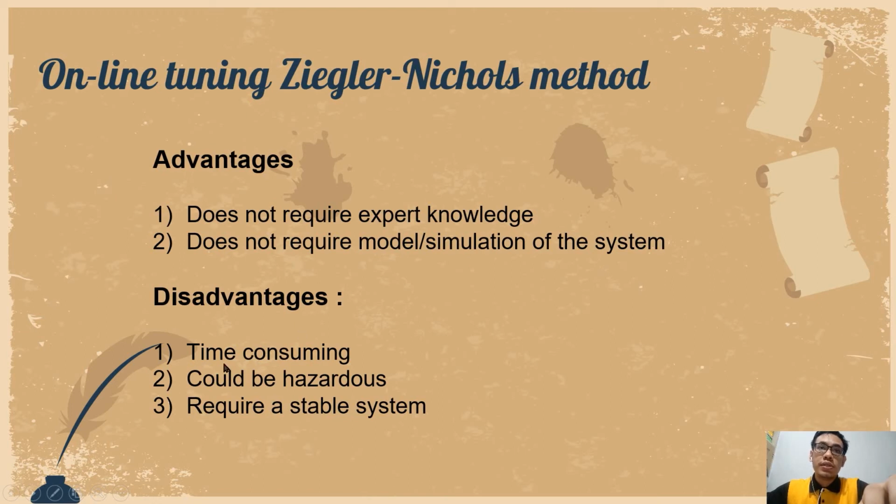For disadvantages, it's time consuming. Why? Because if several trials are required and process dynamics are slow, the long experimental tests may result in reduced production or poor production quality.